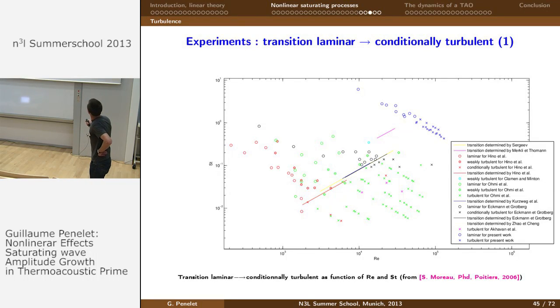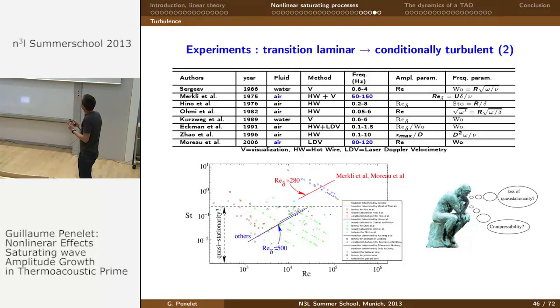So here I show a stability diagram obtained by different authors. These lines correspond to the transition to a conditionally turbulent regime. So this is laminar, this is conditionally turbulent. What we can see here is that these results, which were obtained by Merkli and Thomann, and which have been confirmed by a French team recently, show a transition line that is different from the one obtained by many other authors. Now, if we want to understand more deeply why, we...